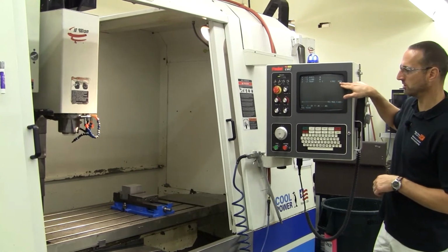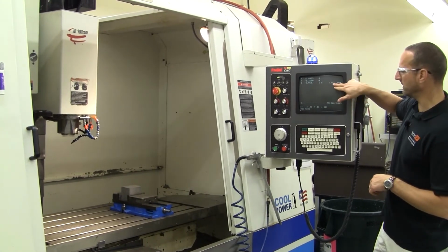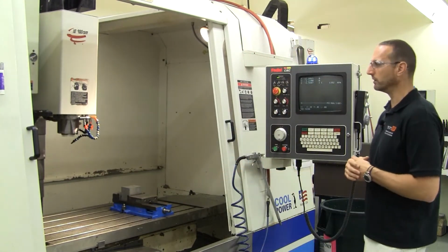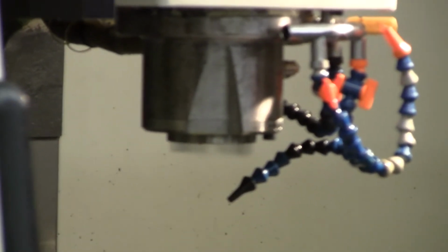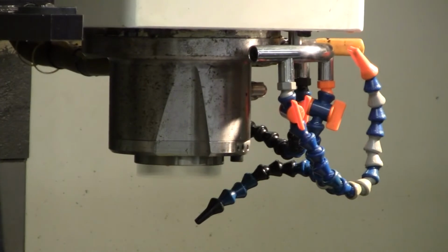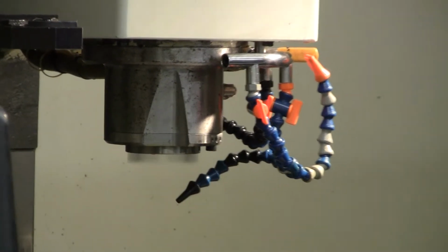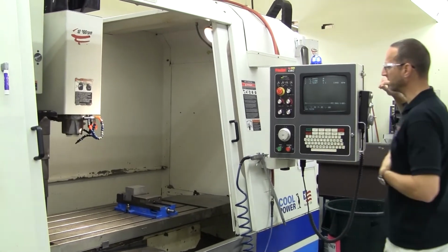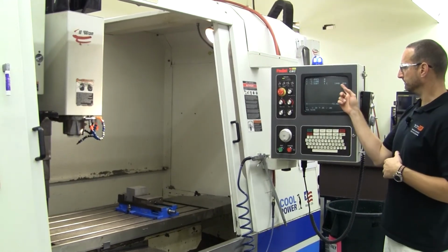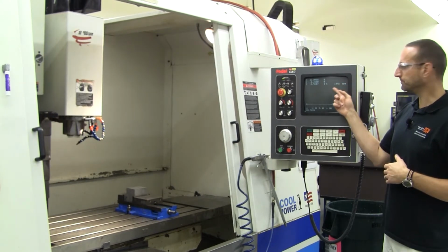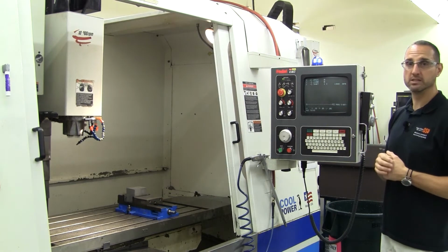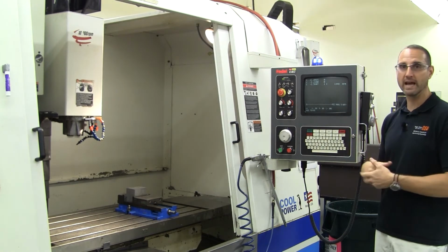Spindle RPM is shown here. And so even still in jog mode, we have indication of spindle RPM, and then hopefully you can see that we are spinning the spindle. And then again, override is active, so I can change my RPM higher or lower right there directly using the override key. Now, the thing to note, the value that it is spinning, or the RPM that it's spinning, is going to be based upon whatever was programmed last.